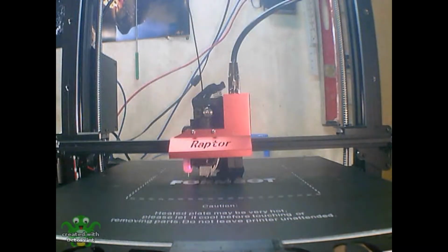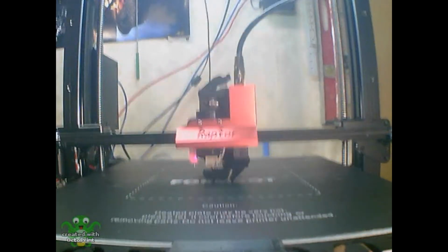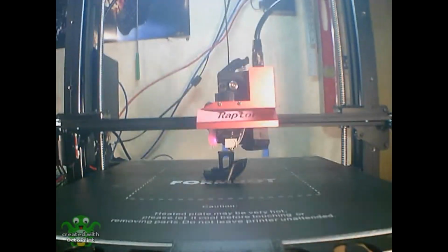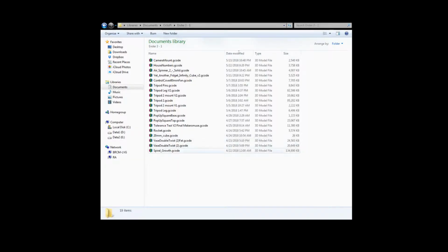And the job of the slicer is simply to slice the model and then generate the G-code for your printer. Slicing the model means it's generating all the commands needed for the printer head movement, the bed and axis movements, and the speed that it prints, along with all the extruder commands to control filament flow, and everything that your printer actually does when it's printing. And it does this for each layer for the entire print. The code that's generated is called G-code, because the extension on it is .gcode.